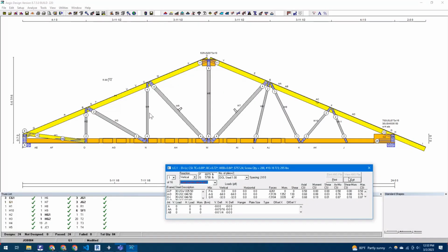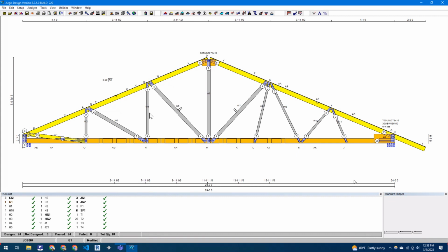Steel, you can get away with it that way. I've heard of people doing it. You don't even have to put a scab in it. It's just like a simple connecting piece they use. No, you just set it up to where there's a splice where you want it reconnected. Build the truss in parts and come out with it. You can do that if you want.